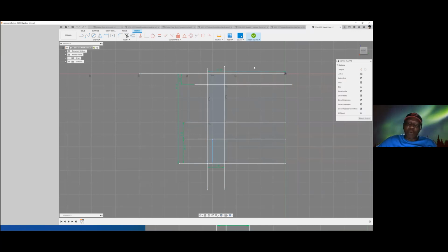So now what we want to do is turn all of these things into construction lines, not the dimension lines, but the lines we have drawn. The dimensioning is done to make sure we know precisely what positions these things are at. You can see that this one is dimension 32. So this line here is at 32 from the origin. And then this horizontal line is 4.5 below it. And then the last line is 37 below the original horizontal line. Then up 10 there, we have this. Then up 7 here, we have this.